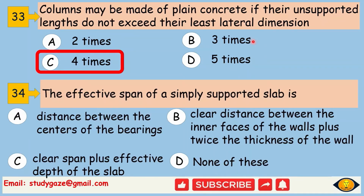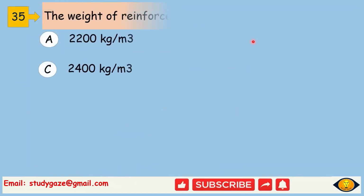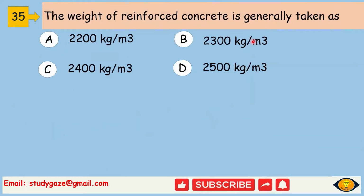Next, the effective span of a simply supported slab is the clear distance between the inner faces of the walls plus twice the thickness of the wall. Next, the weight of reinforced concrete is generally taken as 2500 kg per meter cube.